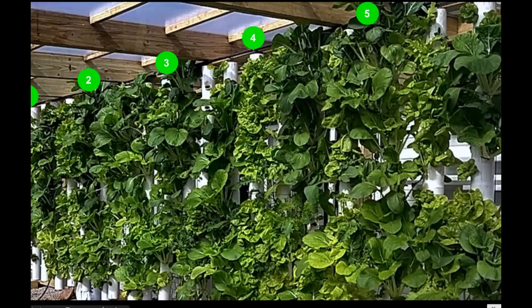But one of the issues that I mentioned already before on the aquaponics webinar is the issue of when you're pumping water into all these towers with just a simple on-off pump. Turn it on in the morning, turn it off at night. All the little exits from the main feed pipe, which is only a half inch, we're going out through 1/8 inch little couplers to each of the towers, and those things clog up constantly. So that to date has been the number one source of the maintenance time on this system. It's like I go up there and have to unclog those plugs frequently. Like right now it's every couple of days.